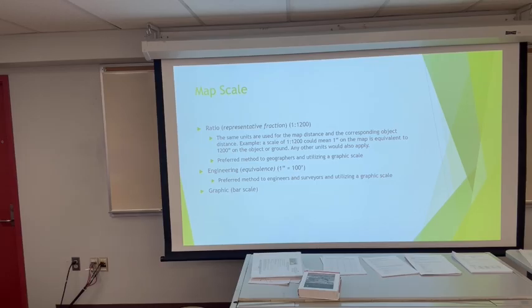So if you are doing some research on a boundary, you go pull a deed. If there was a survey done on that property, it should be there with the deed. I think it's a great idea. Unfortunately, in Ohio and Indiana, if you want to do something like that, you pull the deed. The deed might reference a survey. The deed might not reference a survey. You've got to go to the engineer's office to see, is there a survey on that property?